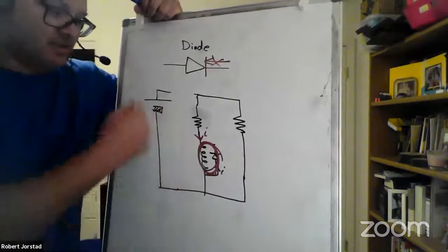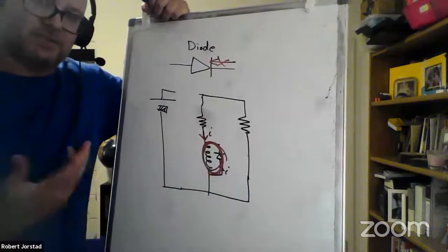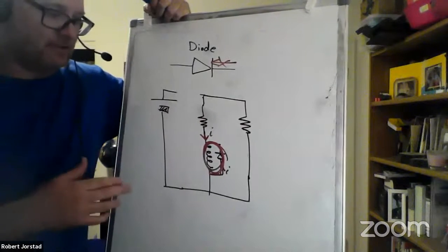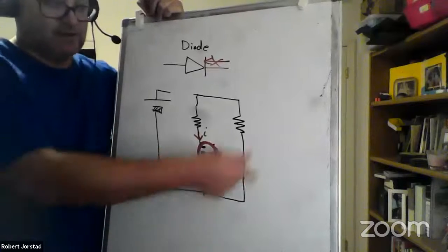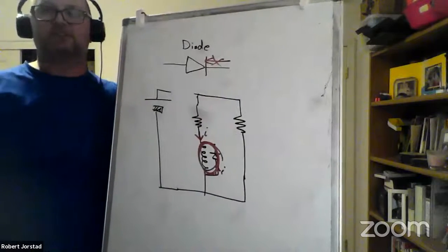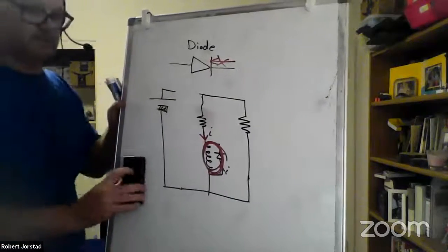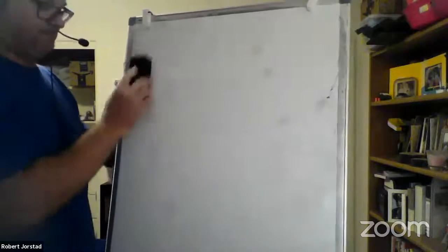But essentially, you could just throw that diode in there, and that gives the current a path for this inductor to discharge. I should be careful: de-energize, right? So you could de-energize the inductor this way rather than having to go through this huge outer loop. If you want, you could read about flyback diodes and see pictures of fried circuit solenoids here. But yeah, that's the idea.